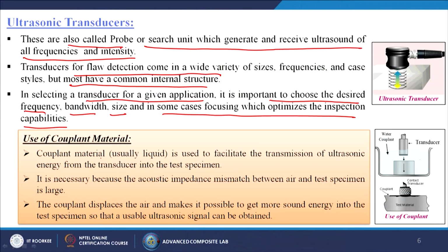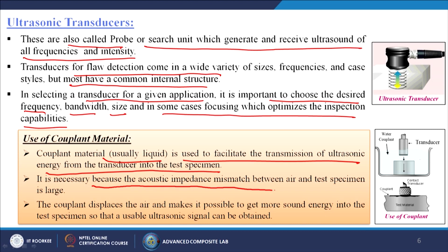Use of couplant materials. Couplant material, usually liquid, is used to facilitate the transmission of ultrasonic energy from the transducer into the test specimen. It is necessary because the acoustic impedance mismatch between air and test specimen is large.